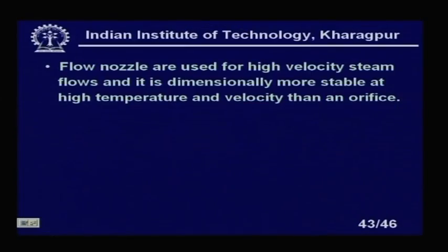Flow nozzles are used because you know that in some situations there are high pressures and high velocity, and sometimes the orifice is not very stable, there is a question of buckling and all these things. In that type of situation you have to use a flow nozzle, and we cannot spend that money everywhere, I mean, to install a venturi meter instead of the orifice meter. So, in that type of situations you can use a flow nozzle because it is cheaper than the venturi meter.